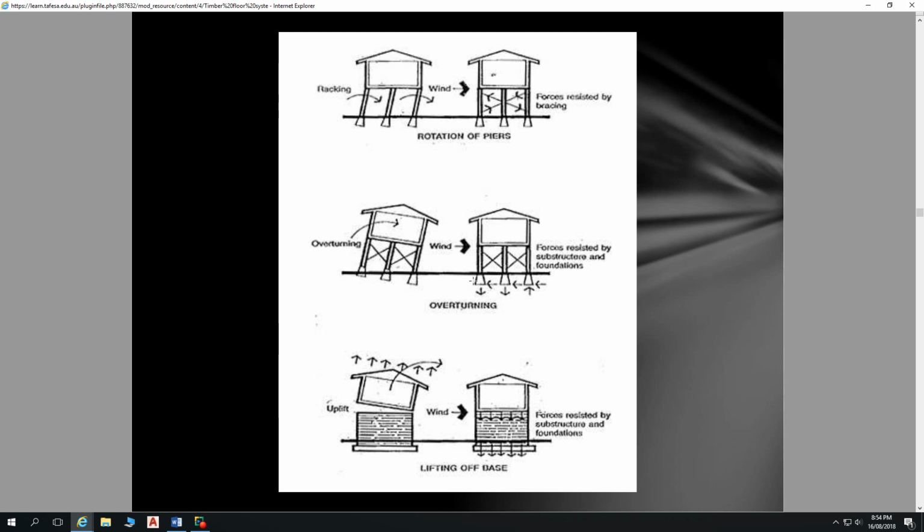Yeah, I'm thinking the same, because with repair and reinstatement of buildings, you see buildings that have been standing there for 50, 60 years or whatever, and then a roof is ripped off. So we've got these wind events happening. It is a very important consideration to over-engineer these things, and we do have wind situations in South Australia where you get quite concentrated winds, where you're building on top of hills down the Fleurieu Peninsula, etc. Winds come off the ocean, hit hills, become concentrated, and provide a great deal of racking force on buildings.